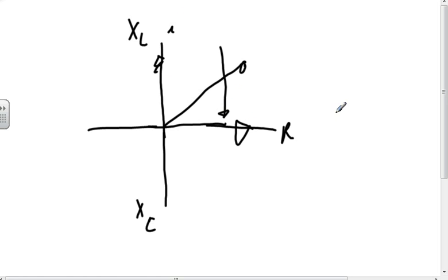Now, if my power factor were 0.8, that would mean I'm paying 20% more for my electricity than I have to. The money is being sucked up in reactive loads going back between me and the power plant.